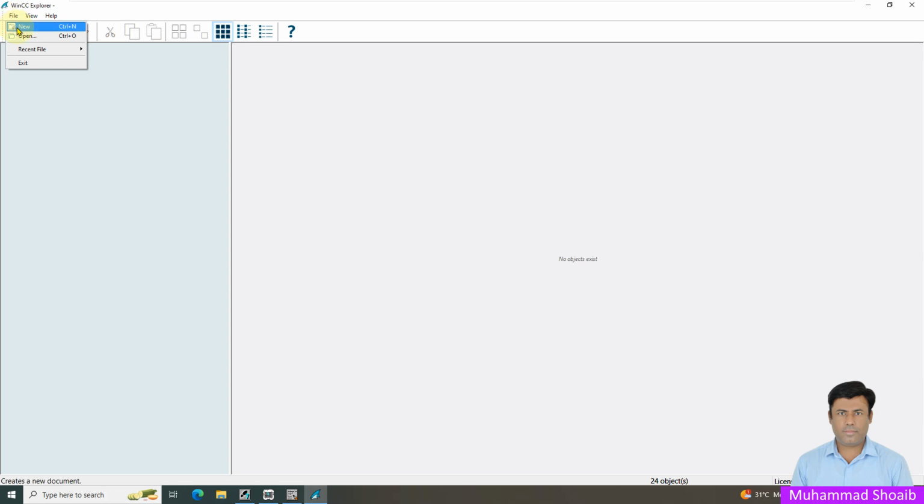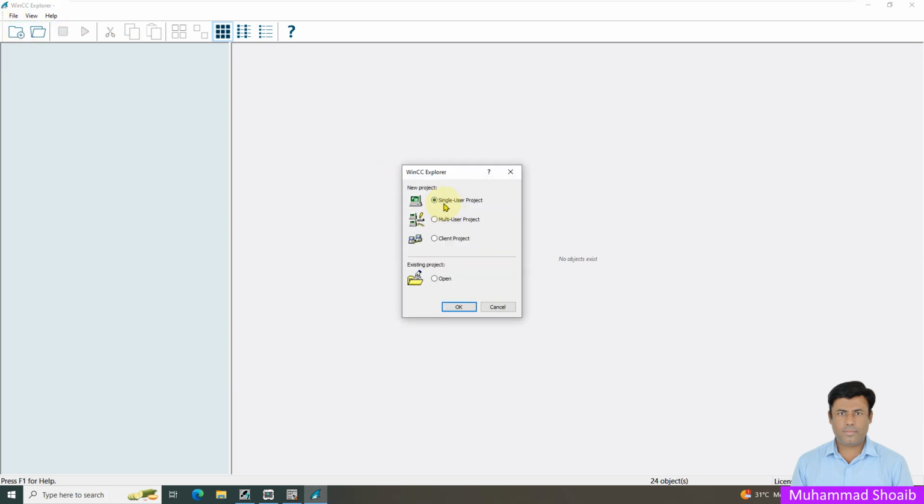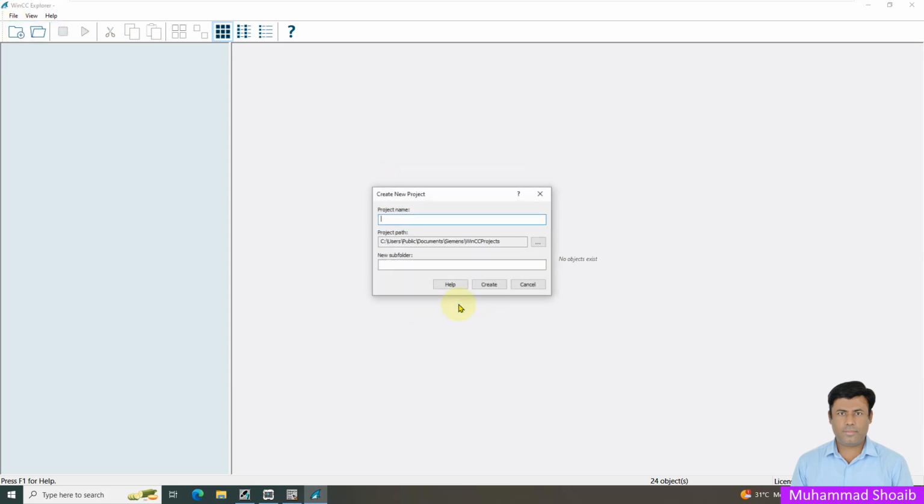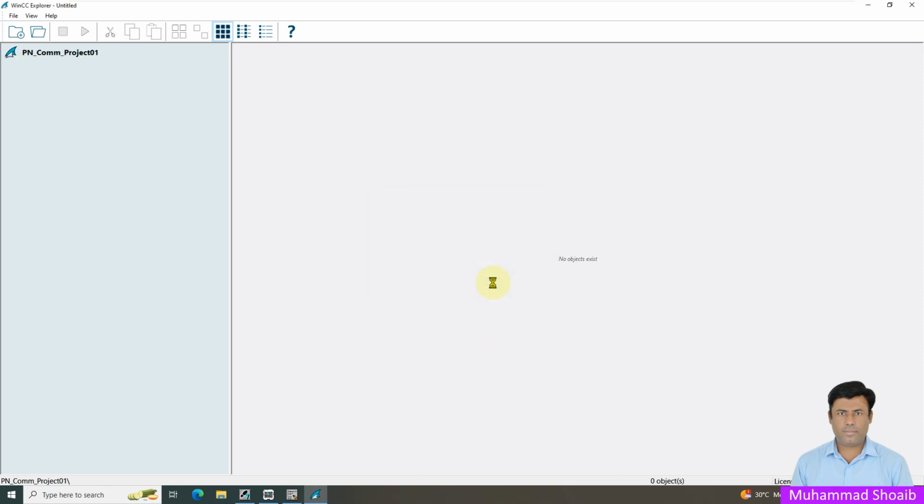Click here in File, New, select the single user project and press OK. ProfiNet communication project 01. Click at Create.